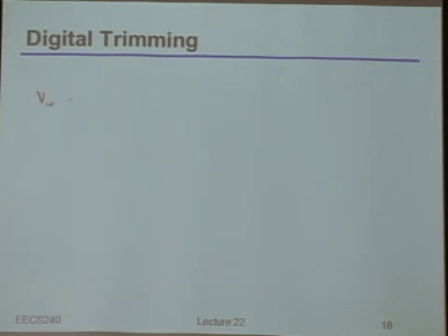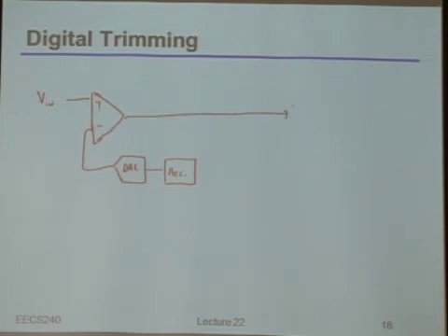I'm going to take my input signal, or more generically something that could be forced to ground, so I can do the sort of offset cancellation. And by the way, this is the sort of trimming idea where we're really only doing this once at the beginning of operation. And so now, as we said a second ago, rather than having some capacitor, I'm going to have a DAC. The output of that DAC will be fed by, let me just call it an accumulator, but really that's just a pile of registers and some additional logic that I'll explain in one more second. This will be my output.